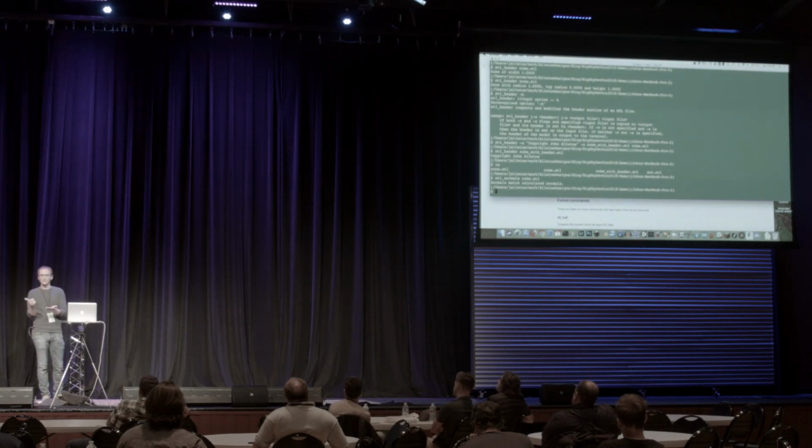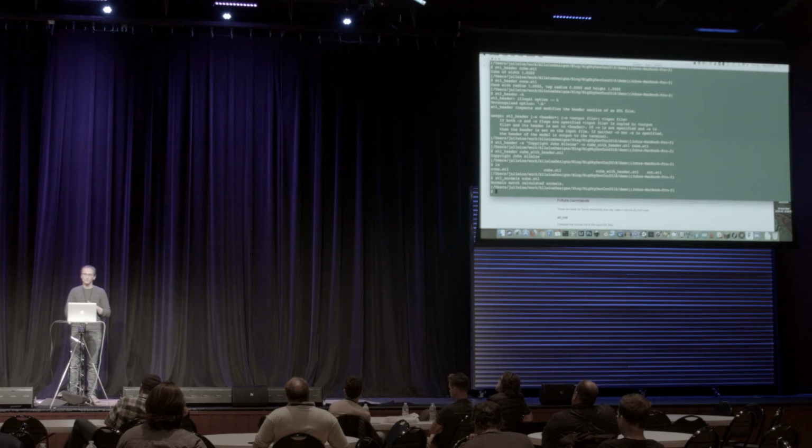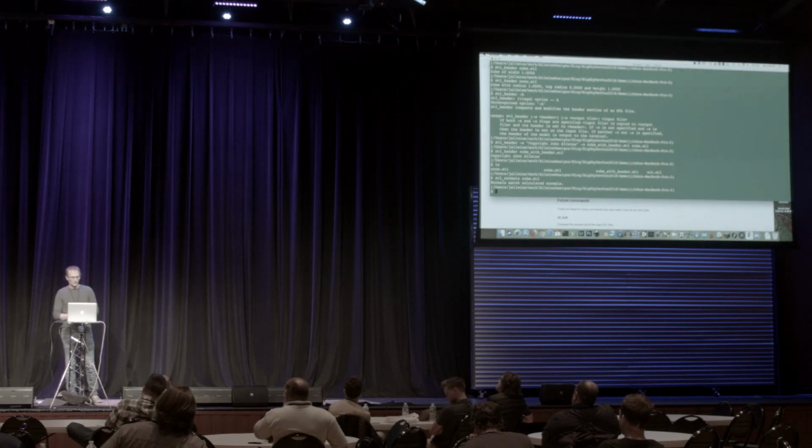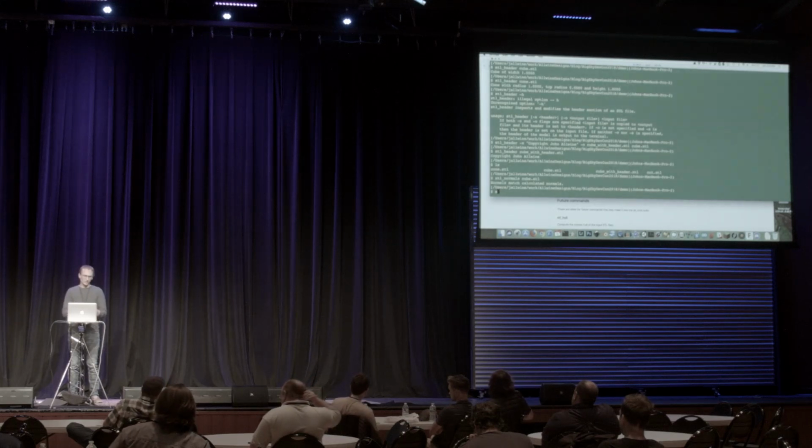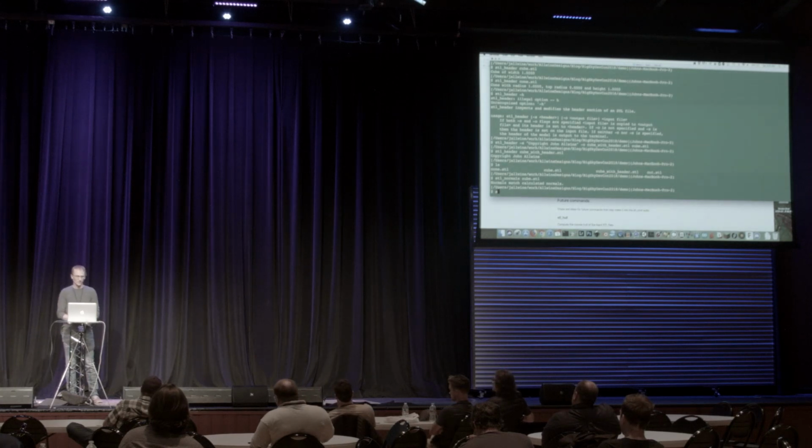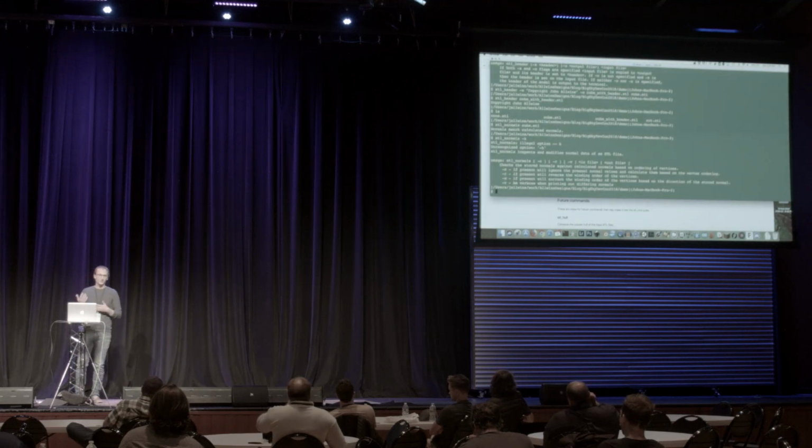So some software follows that convention and just ignores the stored normal there. But if you have a model where they actually had a normal that was useful information and the winding was in reverse order, you can have problems with other pieces of software. So you can inspect that information, and by default it'll tell you your normals differ from what the actual right-hand rule ordering of the points is. And then you can fix it.